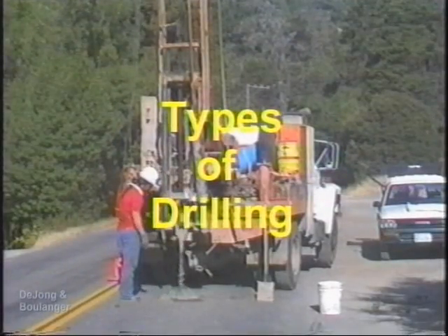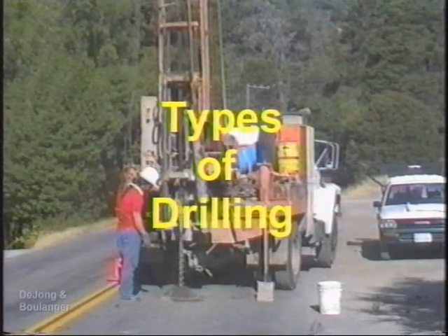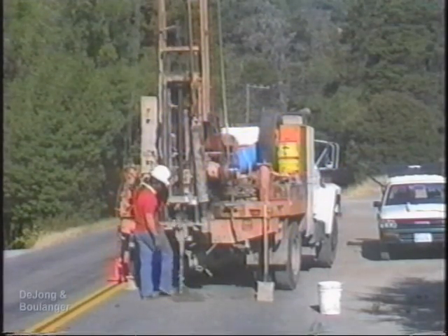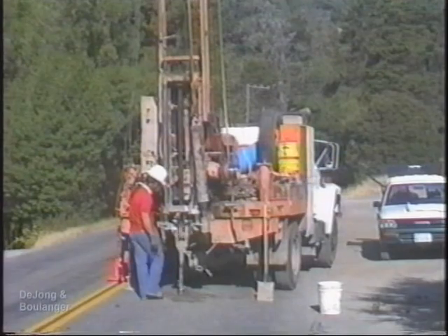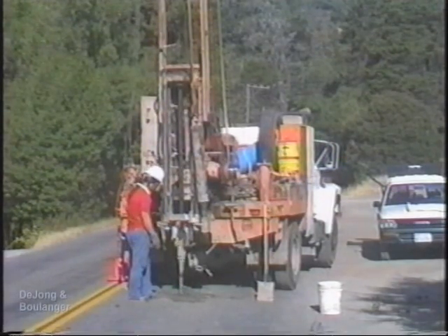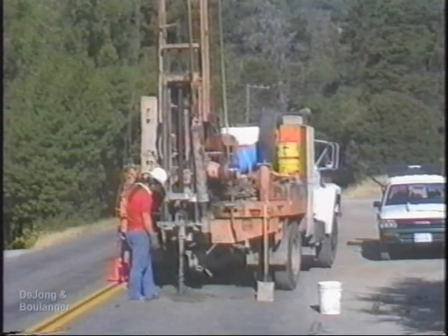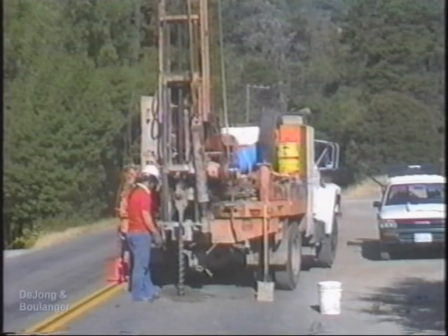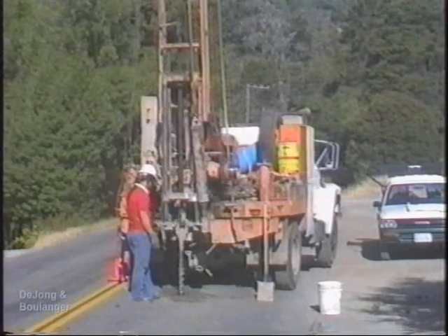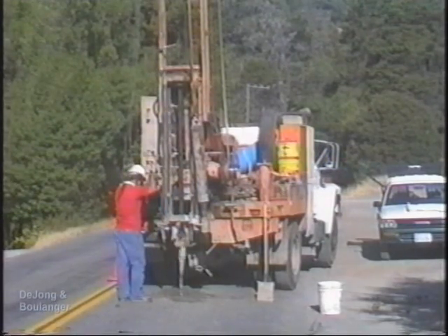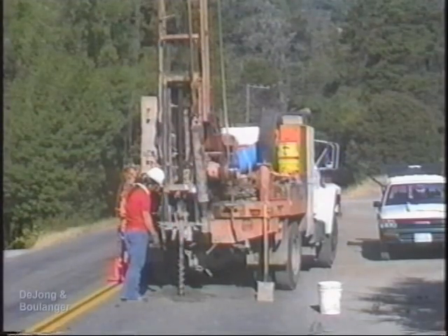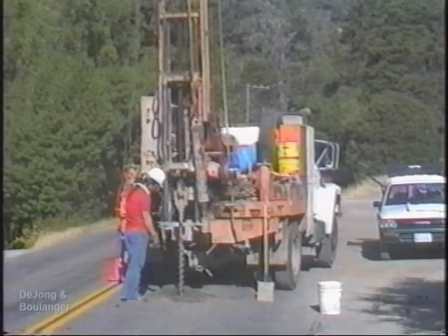Many methods of drilling have been developed, but only four prominent drilling methods will be discussed here. These four methods are solid stem continuous flight auger, hollow stem continuous flight auger, mud rotary, and coring. The main purpose of all drilling methods is to obtain representative samples of the subsurface strata at different depths. These different drilling methods are individually suited to different soil and rock conditions, and thus, more than one method may be needed on a given project.